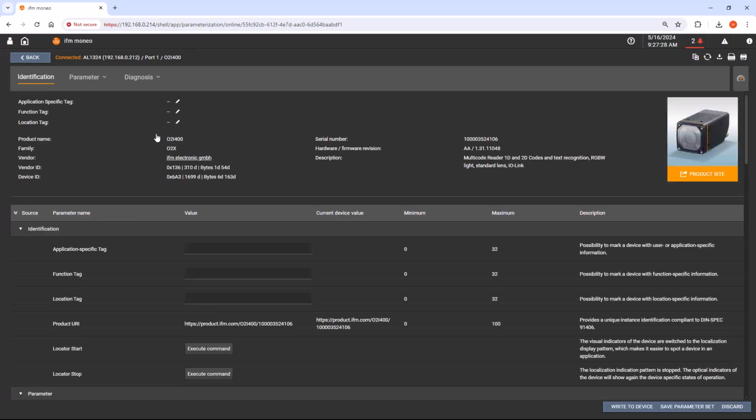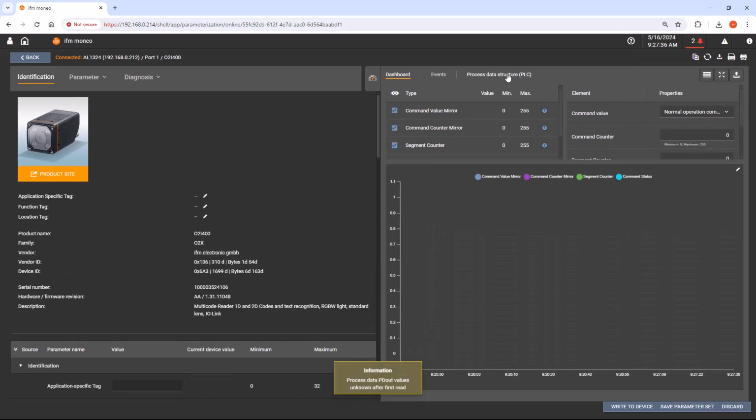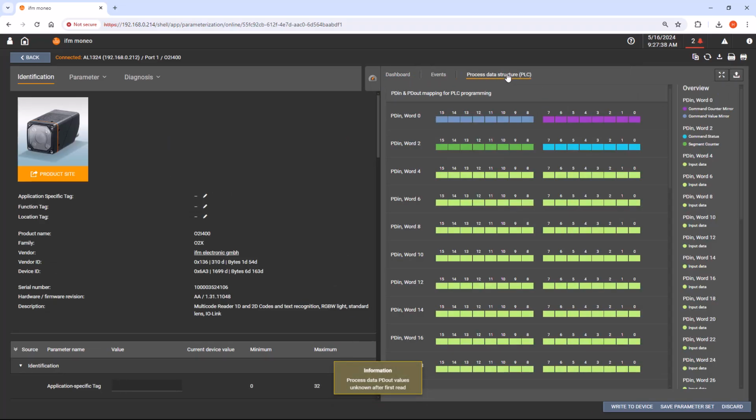When I'm reading in this video, we'll see that I'm reading a PDF 417 type code, and I'm also reading a code that has a large amount of data on it. It has 198 bytes of payload. What we'll see here with IO-Link, we are limited to 32 bytes of data per port.